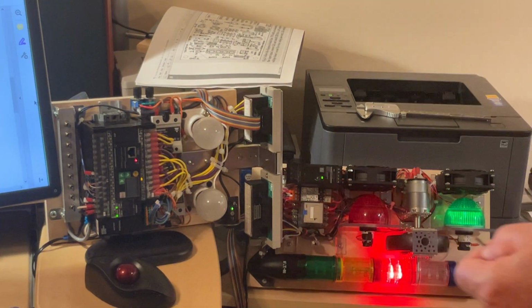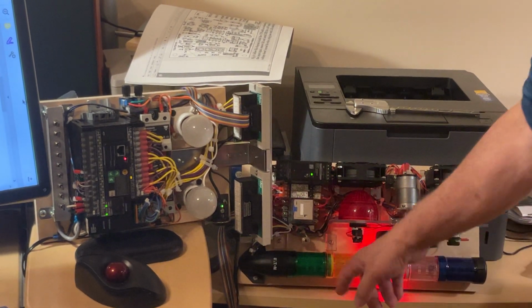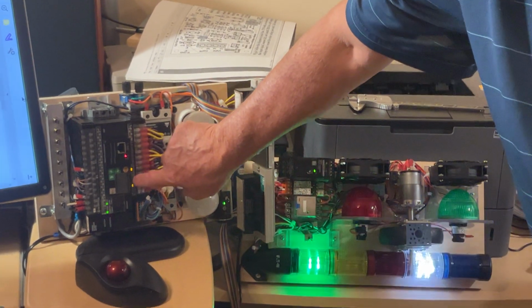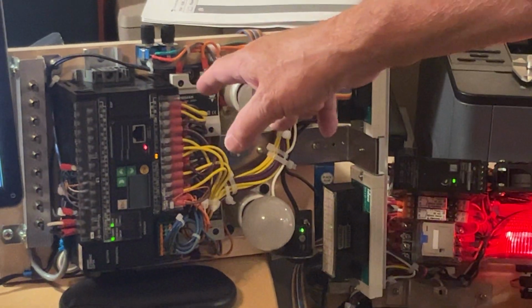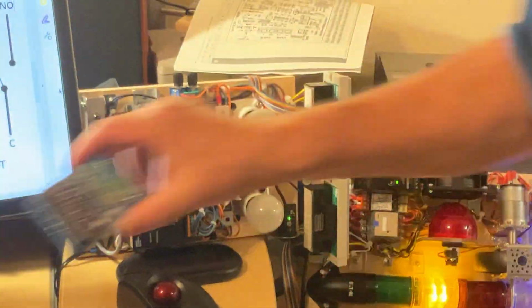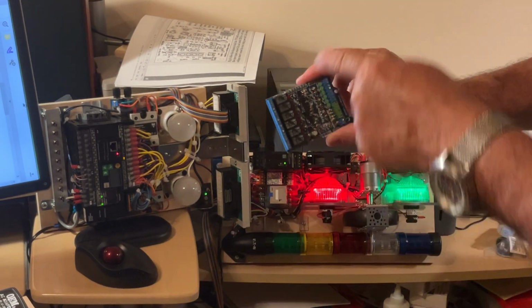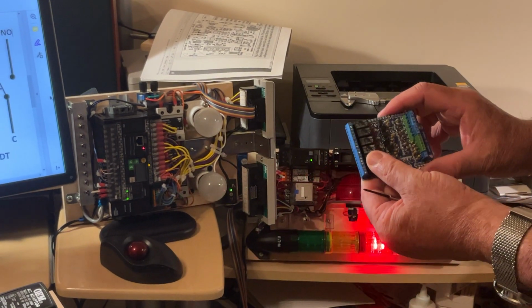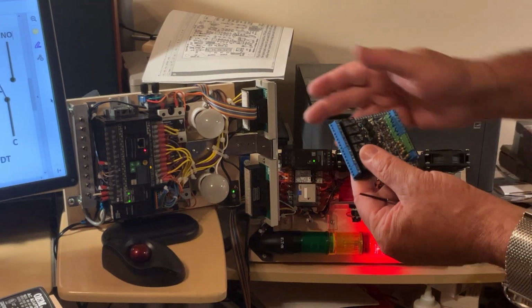When you start it, you can count. Here on the PLC, you can see some lights popping up. And you can hear some noise. The noise is coming from the relays inside the PLC, which are pretty similar to these ones. The size of the relays inside the PLC, they are not bigger than these. And they won't stand more than 1 amp each. So for that reason, I'm using some other external relays bigger than that because you cannot drive a standard valve with very tiny relays.